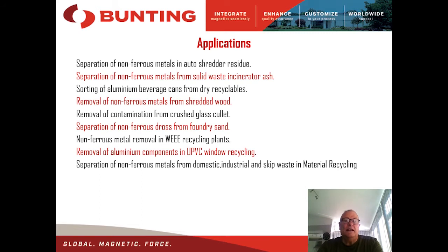There are many applications for eddy current separators in the waste processing industry, and a few examples are in the slide here. We're looking at applications like the removal of non-ferrous metals, copper and aluminium, from auto shredder residue, ASR, which is a product from the scrap recycling of petrol and diesel cars. We're looking at aluminium beverage can processing from household waste, which was probably the initial application for this type of unit.